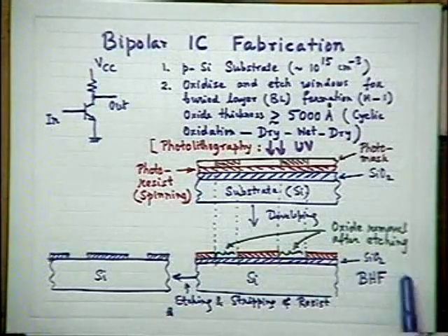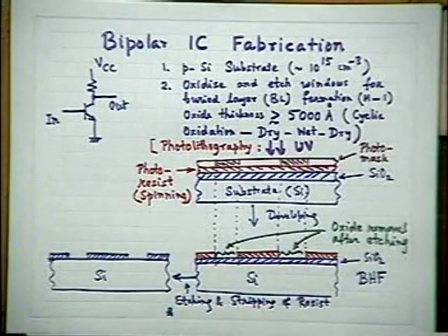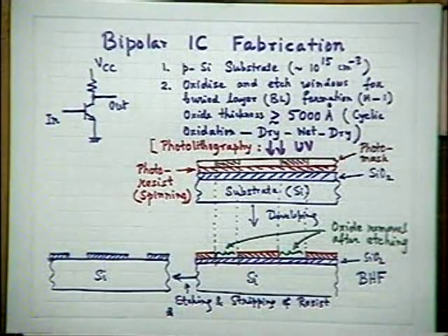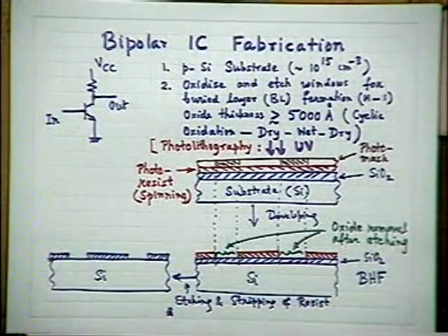Even etching, as I told you, this buffered hydrofluoric acid is the etchant typically used in common industries. But today, even BHF is not being used. People are using dry etching. Dry etching means an etching again which makes use of plasma. For example, if you take freon, freon means CF4, carbon tetrafluoride.